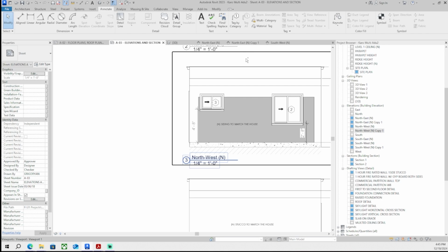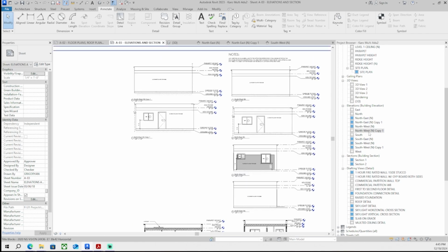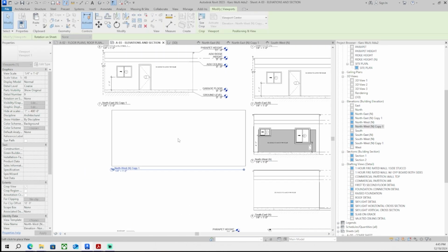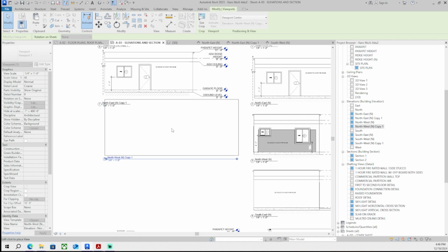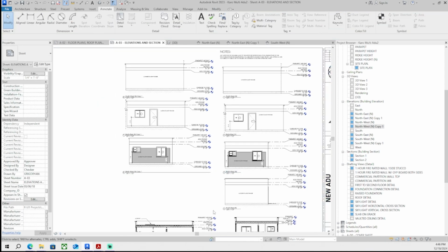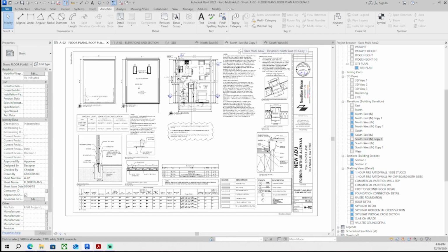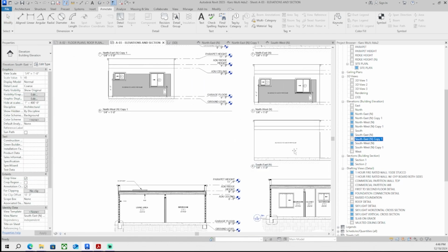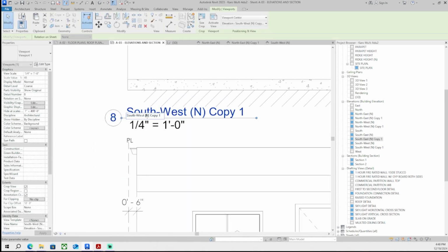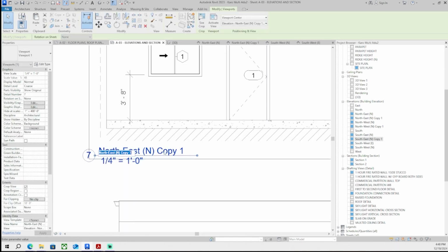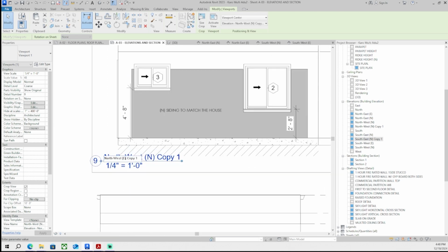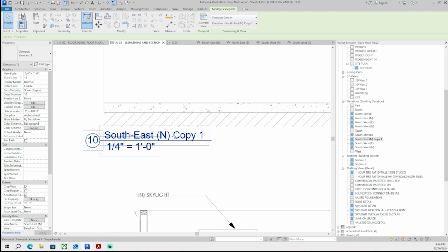By the way, I'm noticing on my elevations and sections, it's not a big deal because we have details zoomed in for it, but on the parapet, I have the downspout, the edge of it, at the top of the parapet where it should be at the bottom. So thank goodness that there is the detail where I draw it correctly. But see, that's the thing with these documents, we really need someone to watch them over.